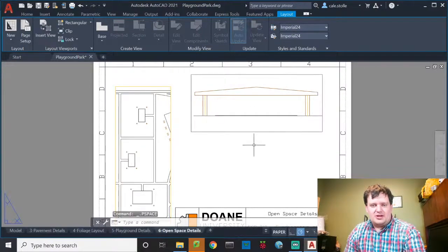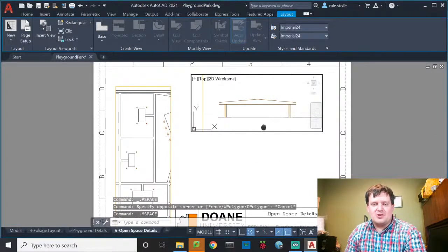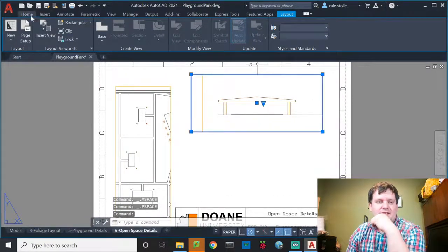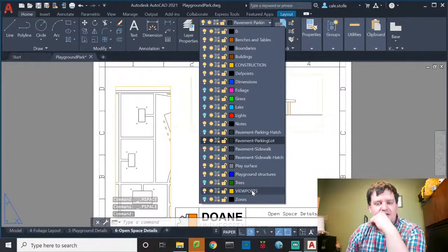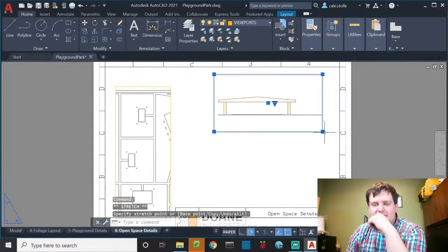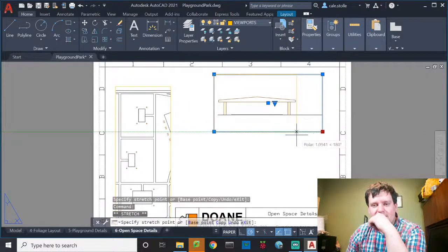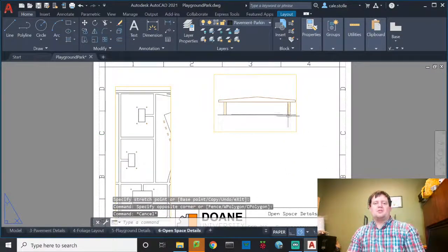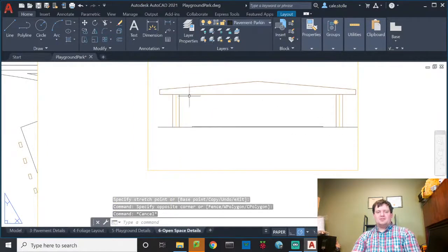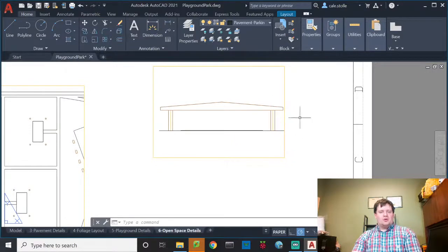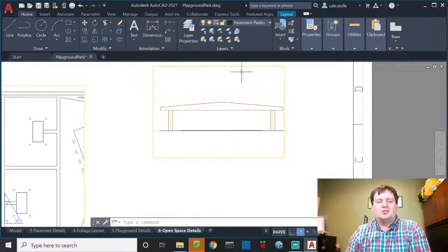My other one's a little bit bigger, so if I use the same scale for both of them, I should probably make this just a slight bit smaller. Okay. Now, first you have to put this on the viewports layer. If you don't, it'll end up with a rectangle around it, which I don't want. I'll bring this in close because I didn't cut off the ground there. I want to cut it in close so that it at least looks similar. Or I could go back in and actually cut the ground there, but I'm lazy.